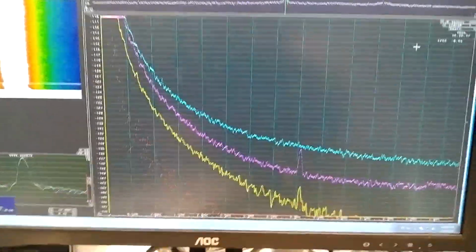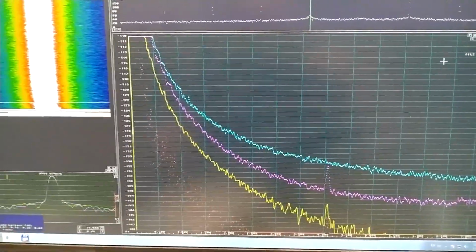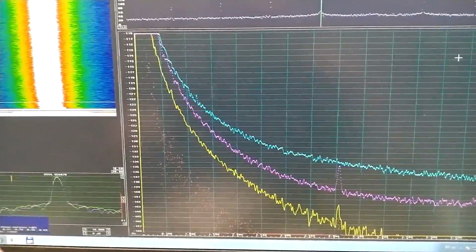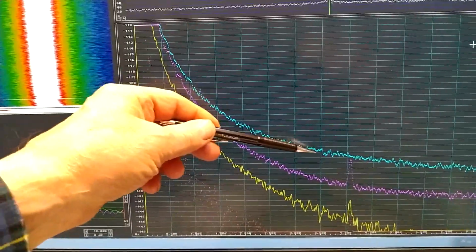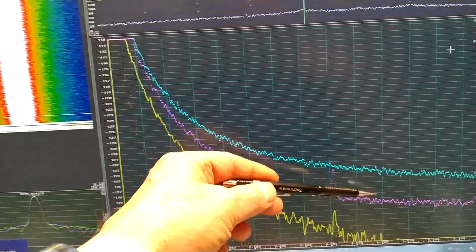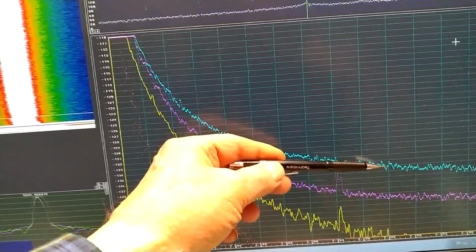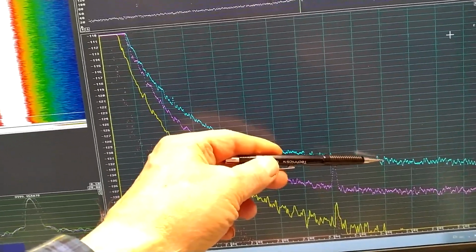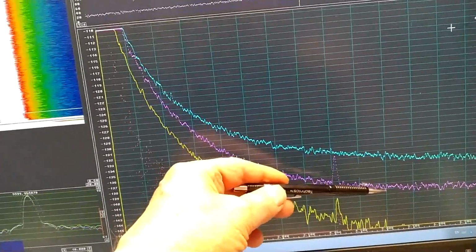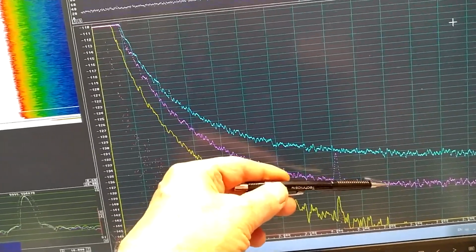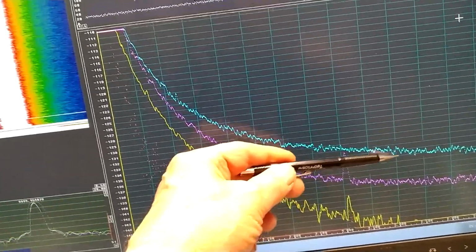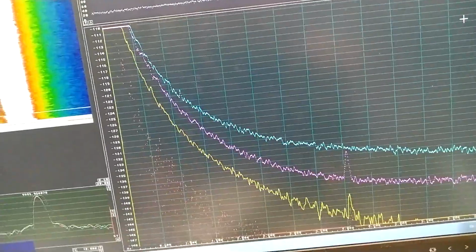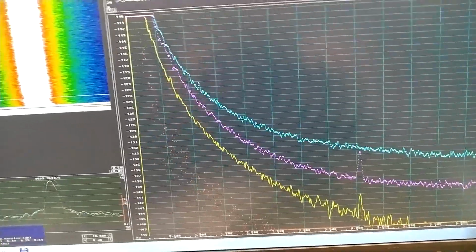The blue trace is the channel 1 oscillator, the one that I modified in the previous video, and it has bipolar transistors, and it is significantly worse than the channel 2 oscillator. This is 5 Hertz, and it is 1, 2, 3, 4, 5.5 decibel that differs.